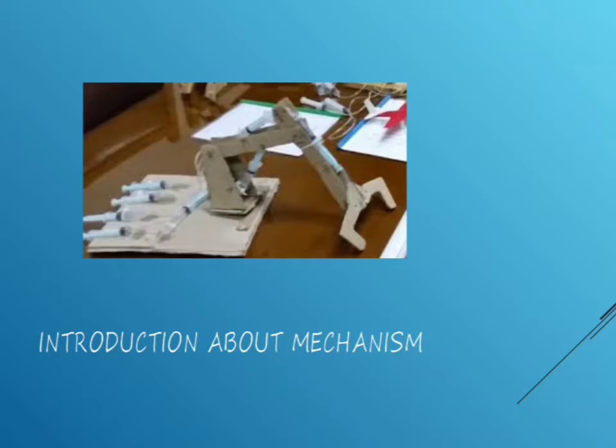Number two is parts. In the mechanism, each part has been provided with certain degrees of freedom to move in a constrained way to guide other parts and also to pick up small weight items and to place them wherever required. The complete mechanism consists of a fixed vertical link, or better to say height, and connected to it is another horizontal link which is free to oscillate about the height in an up-down way of motion.